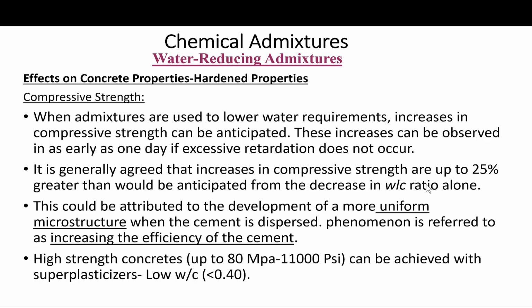So basically, when we talk about high strength concrete, very high strength can be achieved when water cement ratios are lower, below 0.4. Again, the advantage of using superplasticizers or water reducers. To do this economically and without excessive generation of heat requires the cement content to be kept to normal levels while providing an acceptable slump.